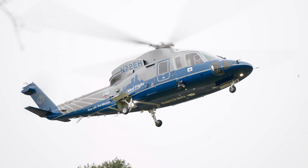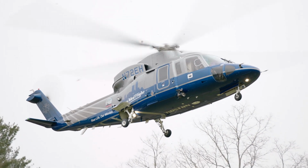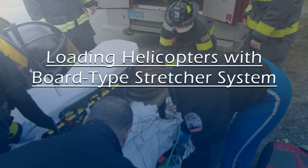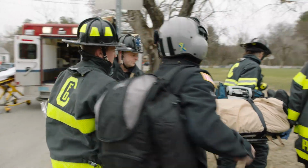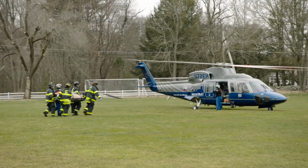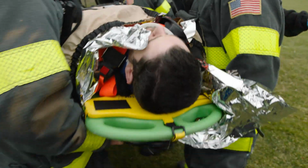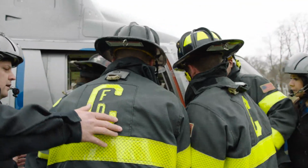The Sikorsky S-76 and several helicopters flown by other operators in Massachusetts use the board stretcher system. 4 fire department or EMS personnel are required to carry the patient on the board-type stretcher to the aircraft. 1 crew member acts as a nose guard, guarding the nose of the helicopter. No one should go behind this crew member toward the nose of the aircraft.